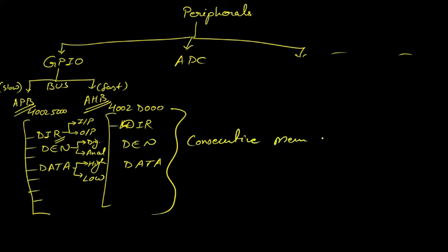You will always find that they have addresses linked in a 32-bit alignment system, therefore 0, 4, 8, C, again 0, 4, 8, C. The last digit will always be the same, because these are 32-bit aligned addresses.